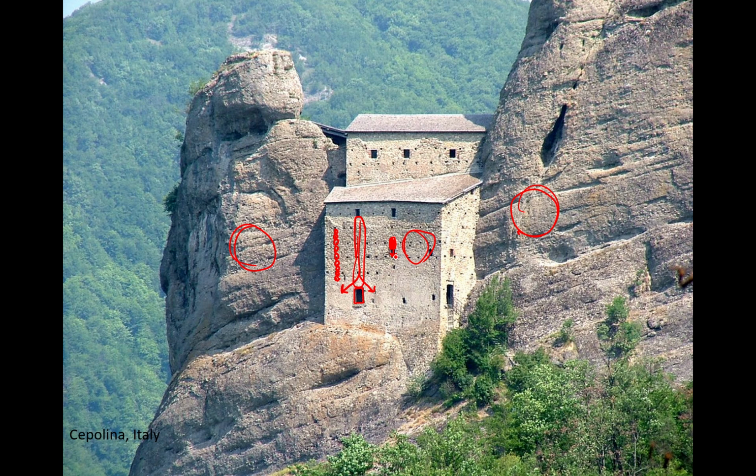So when we look at older buildings, ancient buildings, what we see more often is windows or doors that are more vertically oriented. You could imagine a more modern building might have a big, wide, horizontal window. But think about what's happening with a big, wide, horizontal window. You've got all this weight of all these stones up here, and we don't have a good way to transfer those weights sideways so they can come down into the ground.